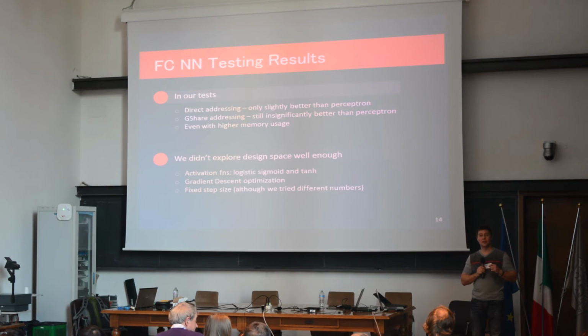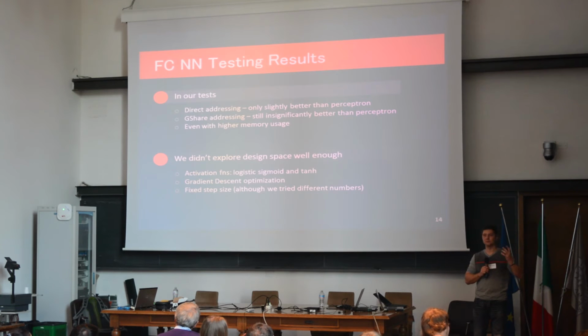And in G-share, you have some global history pattern, which you then do an exclusive OR with the branch address to get the actual bucket, to get the actual branch predictor. So this is just the algorithm of selecting one of the tens or even thousands of units that you have trained on the current program that's running.